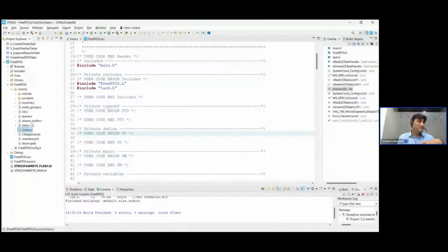Let's say you want to do inter-task communication, you want to do some advanced stuff, or use a queue to solve mutual exclusion, a situation where you want to handle critical data between different tasks. Anyways, these are the real core files from FreeRTOS. Okay, we don't have to write any code at all, we have not yet written any. This is all what we get when we download the code from FreeRTOS.